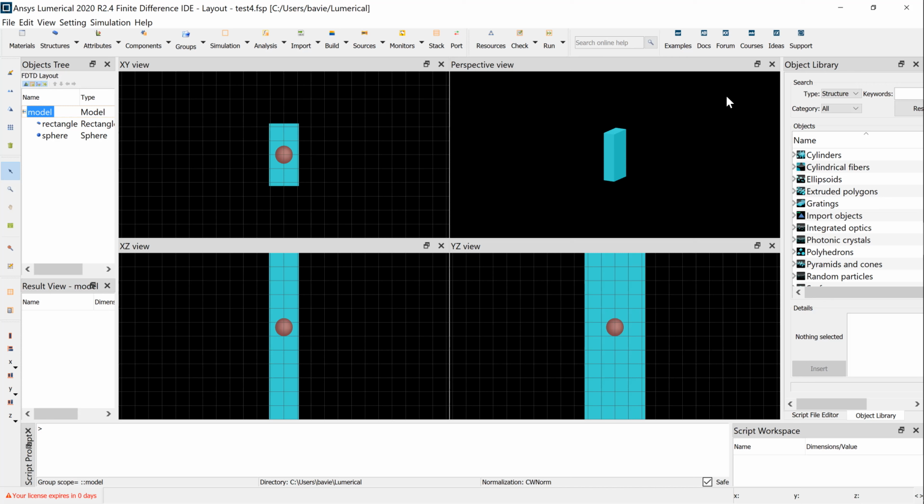for the simulation. To be specific, we have defined two objects in the computational domain: a spherical particle representing the nanoantenna and a rectangle representing the surrounding medium. The next step is to set up an excitation source that performs the role of light illumination. We use a short script similar to how we do in the procedure of setting up the objects.